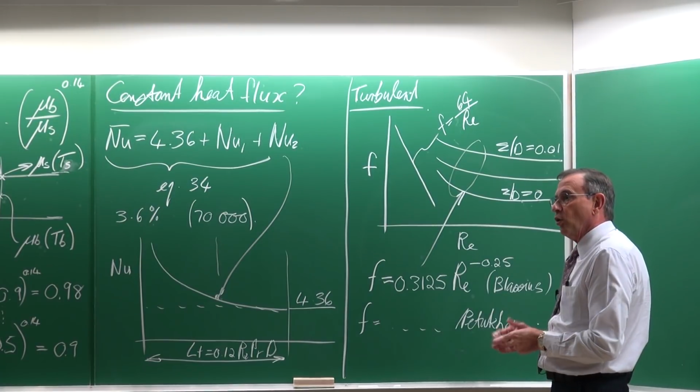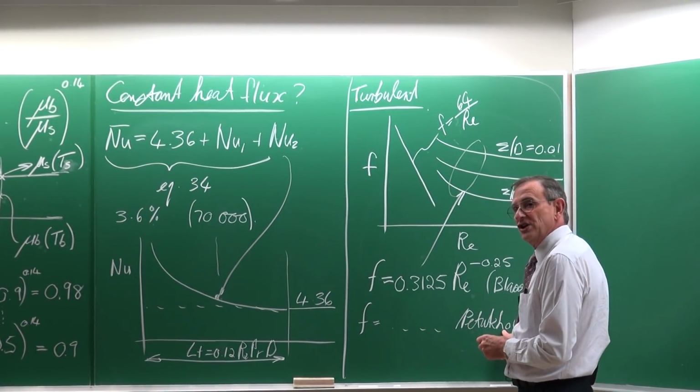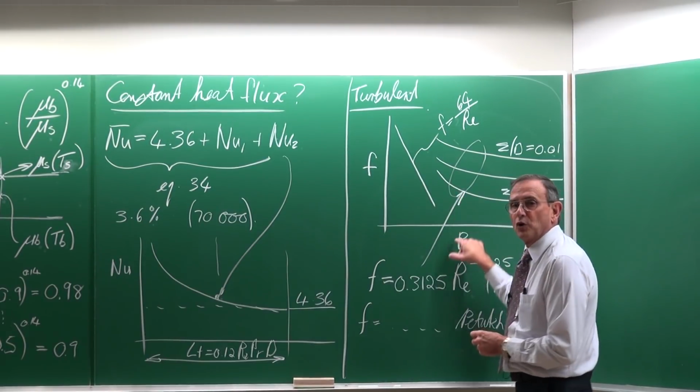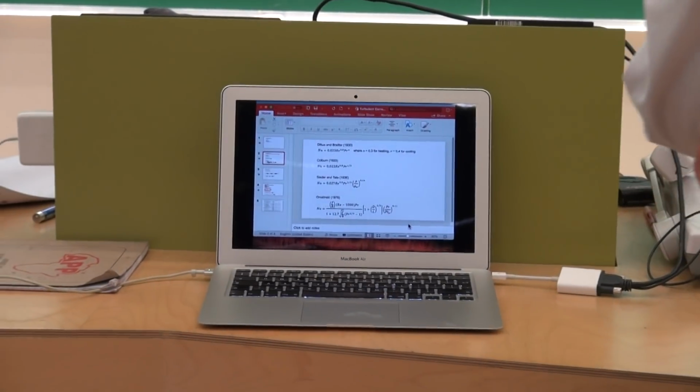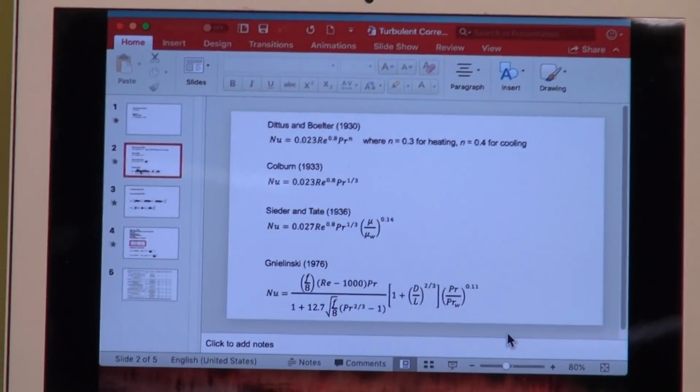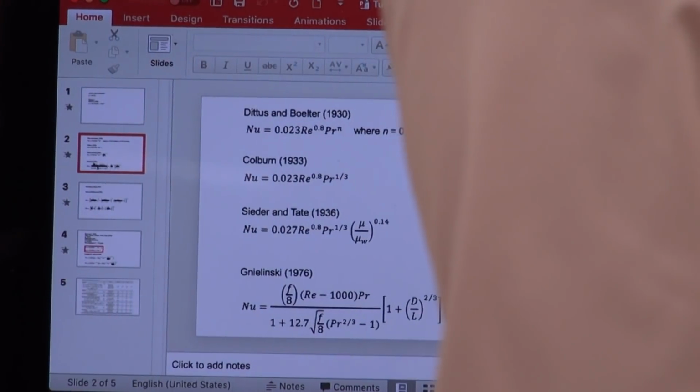However, I always believe that when you use an equation, just go and check on your Moody chart approximately if it is correct, because it's so easy to make an error on a calculator if you're under pressure. Okay, now the very important thing that needs to be replaced is, if you go and look into history, there are so-called many equations that you can use and that has been used in this textbook.